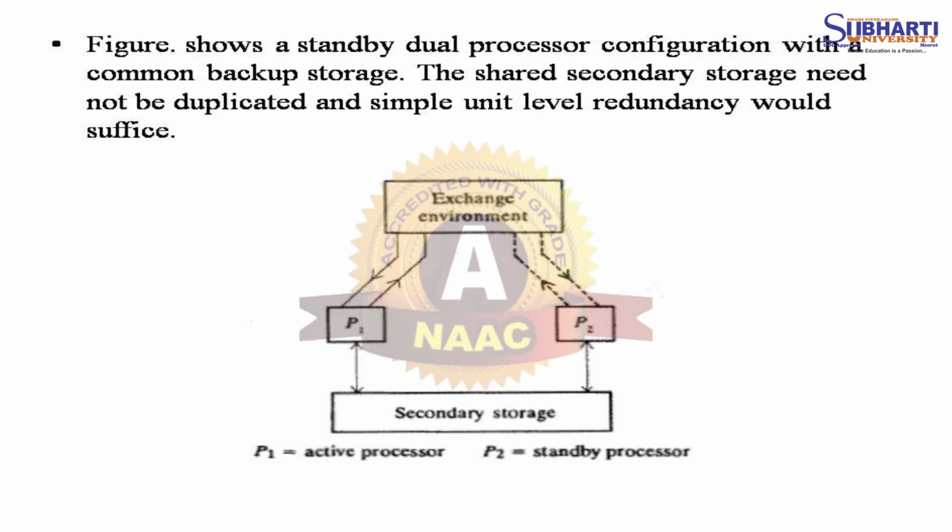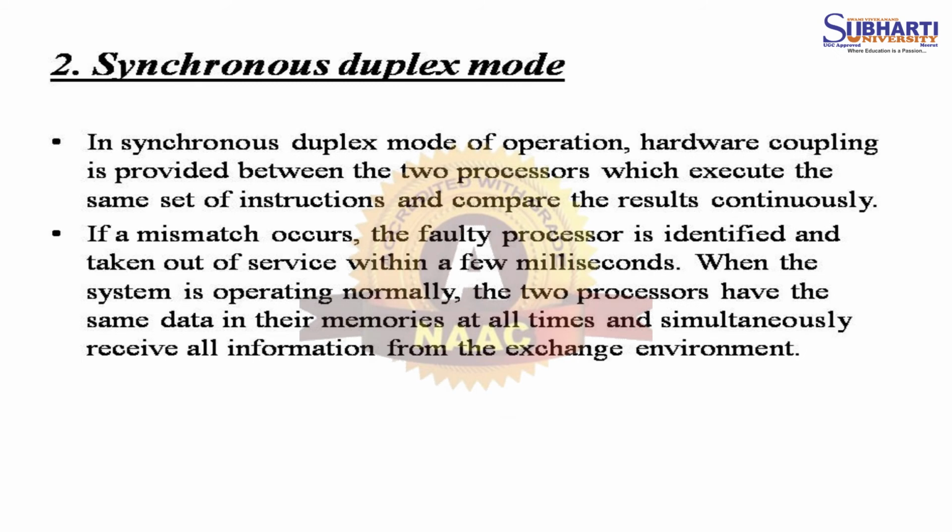Synchronous duplex mode. In synchronous duplex mode of operation, hardware coupling is provided between the two processors, which execute the same set of instructions and compare the results continuously. If a mismatch occurs, the faulty processor is identified and taken out of service within a few milliseconds.